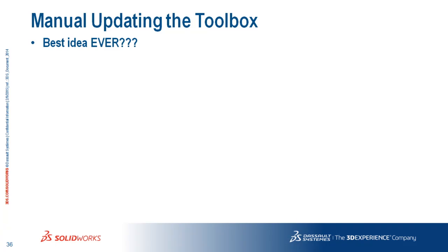No, it's still your file, okay? But instead of telling SOLIDWORKS that it's a toolbox part, it just tells SOLIDWORKS it's a part. So in the assembly model's feature tree, next to a toolbox component you'll see a little fastener symbol, right? When you take that flag off and you go look at that same part, it'll be a yellow T-shaped block. It actually recognizes it as a regular SLDPRT file, as before, okay?